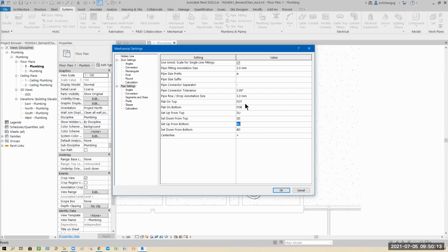But in Singapore, we have our way of presenting. Commonly used, I saw the label is BOD. Bottom of duct, which is here, they don't have. If they have, we can do some changes. So I think it's easy. So all the text size is quite big, 3 mm. So let's say I change it to 2, for instance.